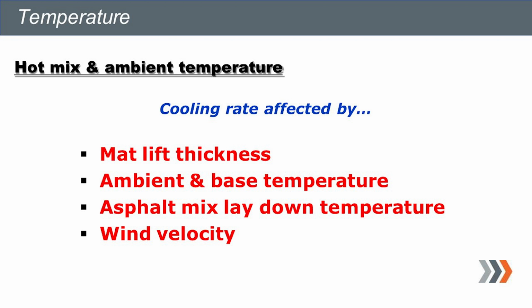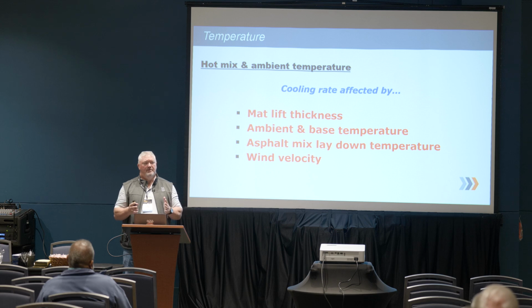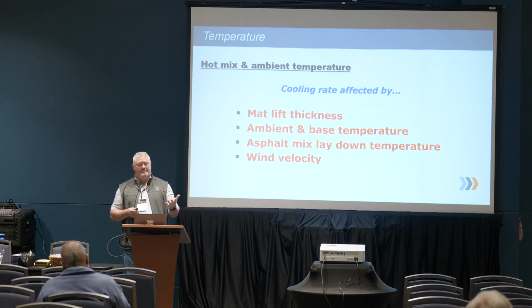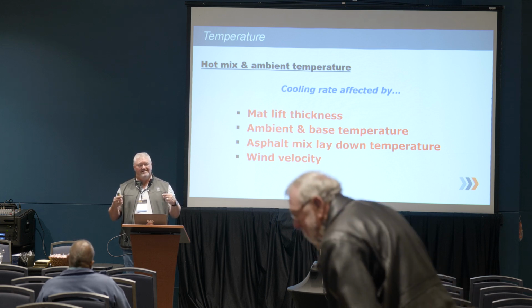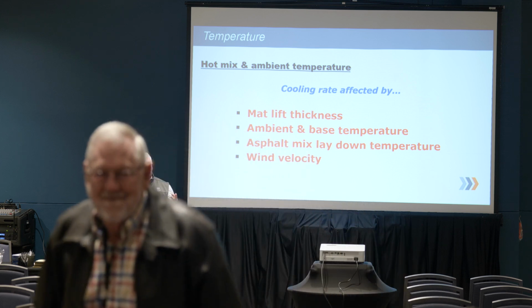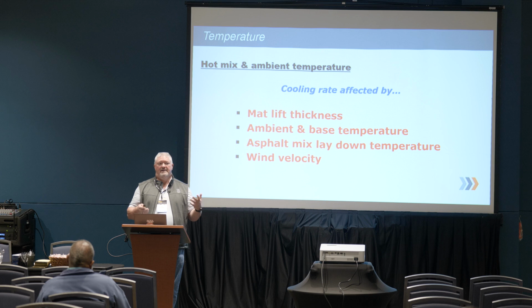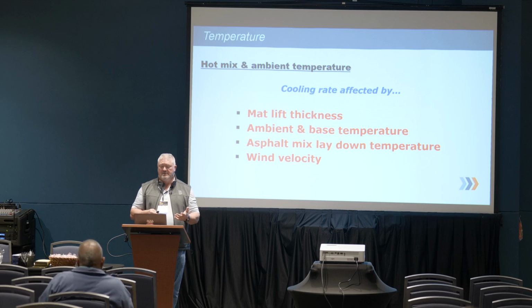Cooling rate effect, we saw what mat lift thickness did for that cooling rate in my time to get compaction. Like I said, our ambient and base temperatures will change morning, noon, and night, but we can adapt to that. Our asphalt mix laydown temperature, that's the only thing we can control from the plant is that temperature. The other two are up to Mother Nature. Wind velocity, a small 5-mile-an-hour wind on a cool day and a thin lift will cool that mat super fast. So it does have a big effect on it.